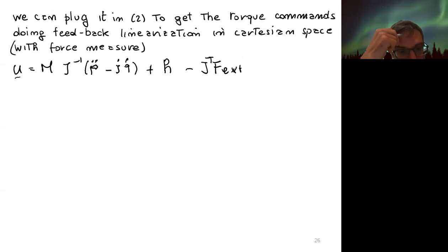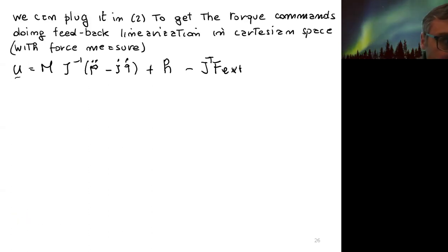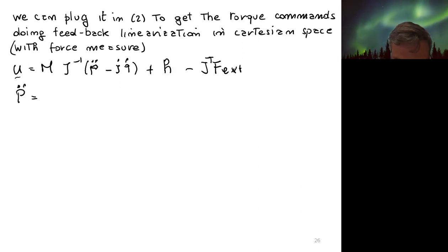And then we take the previous behavior that we defined in the impedance model, and we express the desired acceleration that we want at the end effector. And this acceleration is the acceleration that, in essence, realizes the impedance that we want. So given an external force, a contact force, this is the acceleration that will make our end effector behave as our desired impedance, which is composed of the desired inertia Md, the desired stiffness Kxd, and the desired damping Dxd.